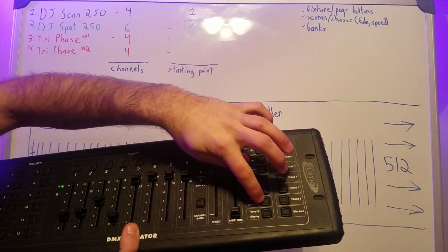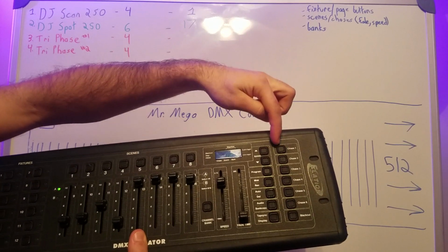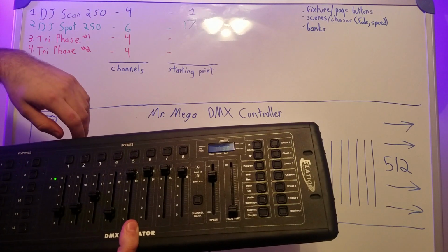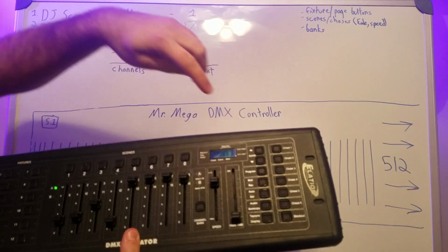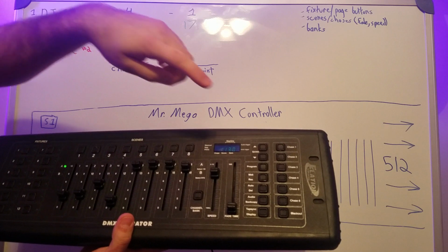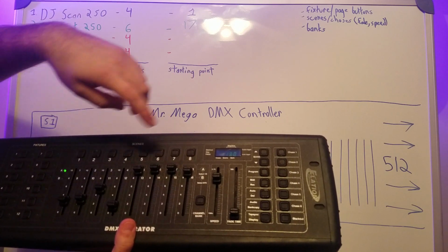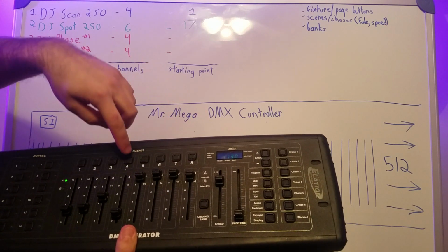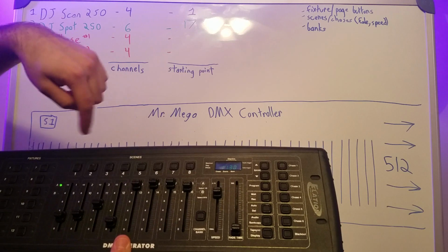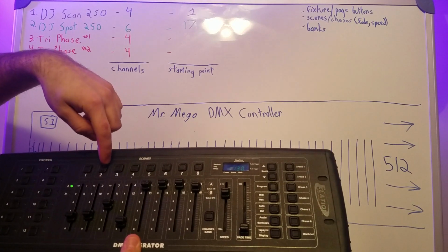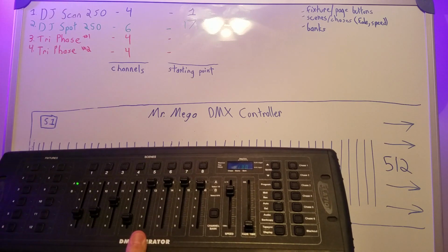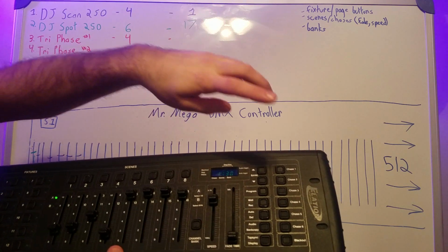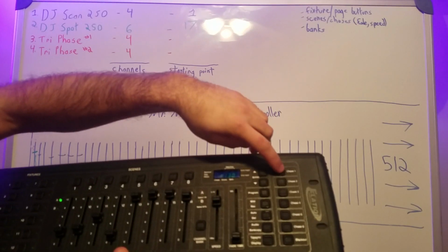what you can do is go into chases here and program chases. A chase is a sequence of scenes, and you pick the order in which you want them. So I'll say chase 1 while I'm in program mode. I want scene 1 of bank 2, scene 3 of bank 3, and scene 4 of bank 4. Let's say I want it twice. So you can duplicate. You can go 2, 2, 2, 2, 3, 2, 4, 2, 5. Then as you have the sequence of scenes that you like in a certain order, that is your chase. And so you can run your chase.